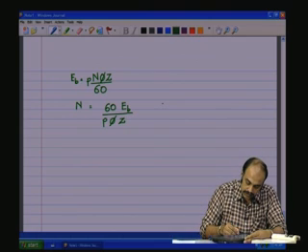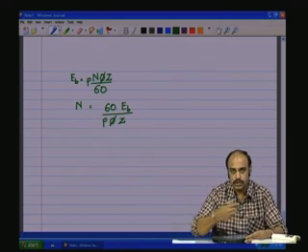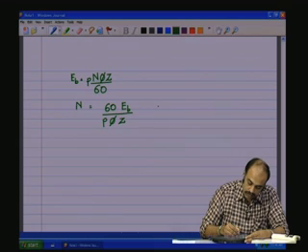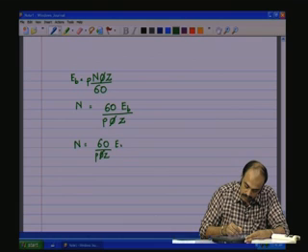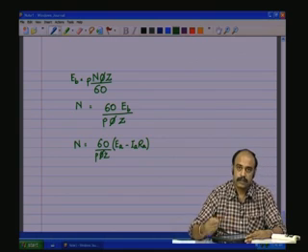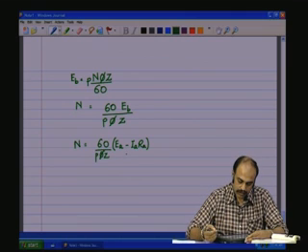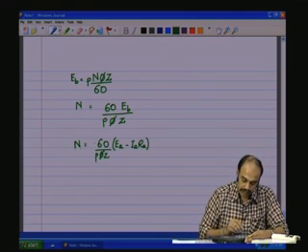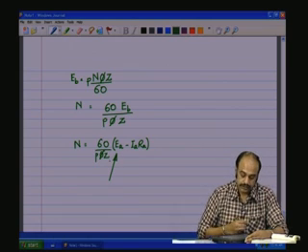But now then, EB is the back EMF, and the back EMF is generally not measurable because the armature resistance is distributed in the armature coil. EB is actually E A minus I A R A. So, this would be the exact speed that one obtains in a DC motor for a given applied voltage.